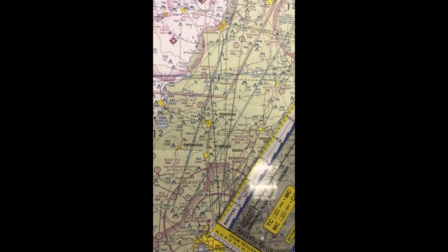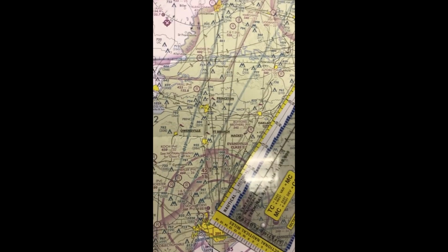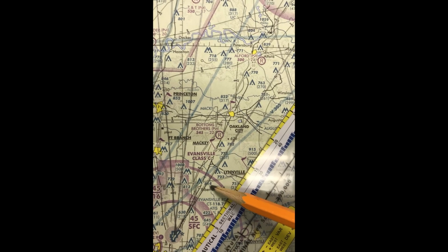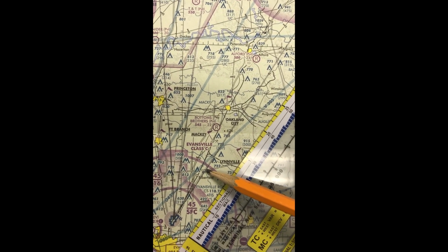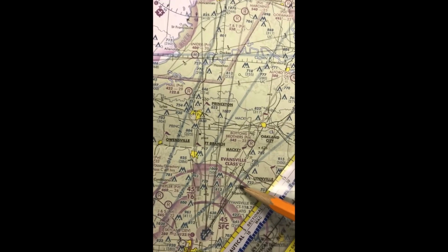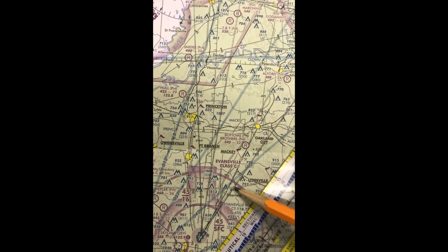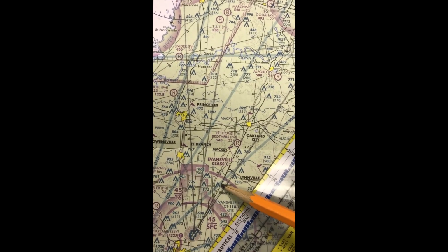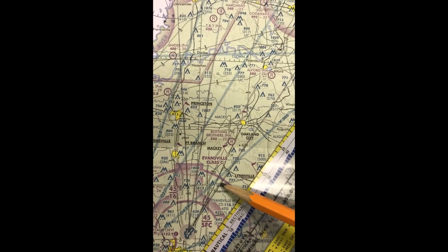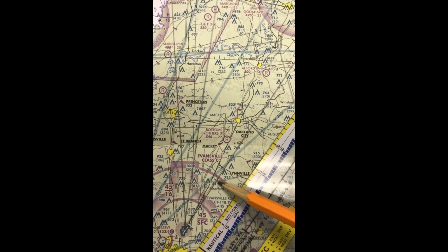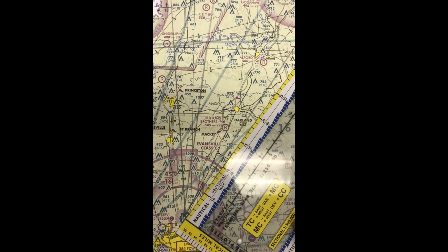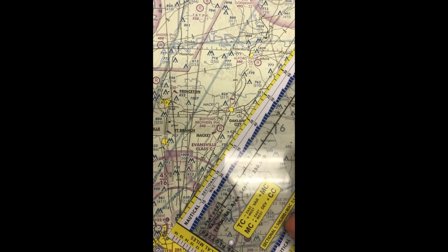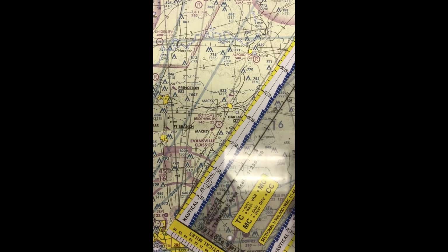Now, once we lay the plotter on there, we can see that if we were flying the appropriate course, that 10 nautical mile reference is going to fall just past Elberfeld along Highway 64 here. All right, so we could potentially use the intersection of this railroad track and this major highway here to denote our top of climb. So we'll go ahead and draw ourselves a little line there, and then we'll go ahead and determine what our approximate course will be for that first leg.